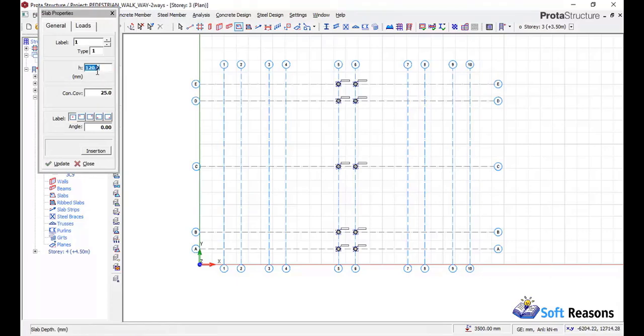So we are considering slab thicknesses. It is a flat slab. We need to provide it with a reasonable thickness so as to be able to withstand the load. Alright, so we'll be having a thickness of 300. The cover is going to be 25 mm. Alright, go back to the load tab. Okay, the self weight multiplied by the concrete unit weight of 24 kilonewton per cubic meter, you have this 7.2.